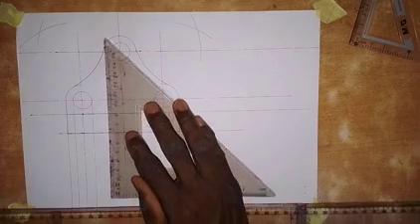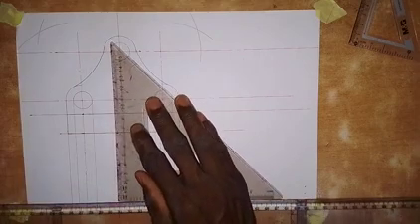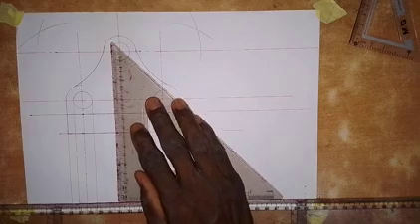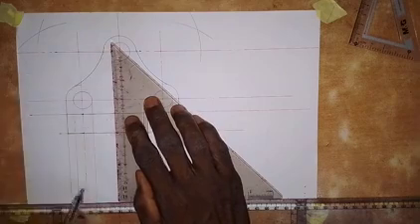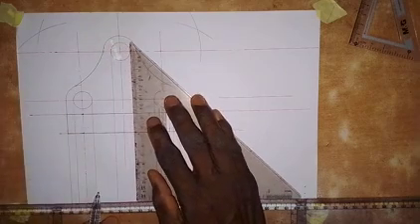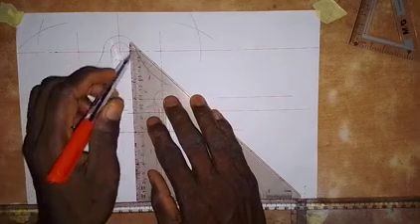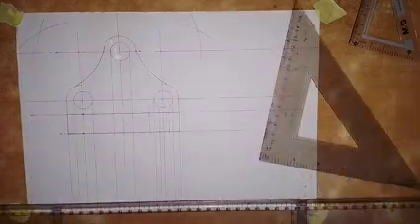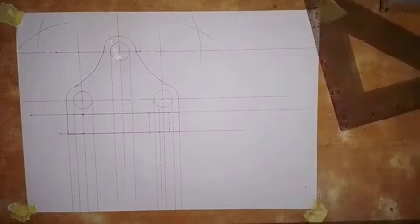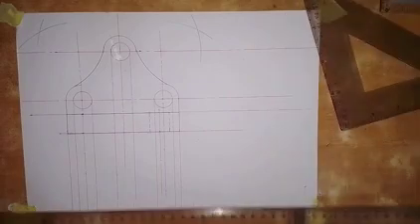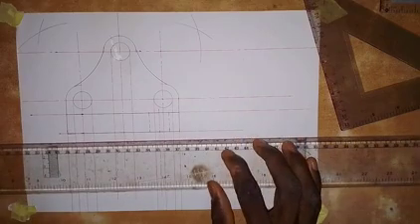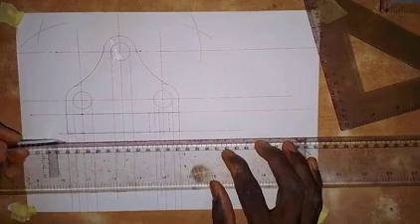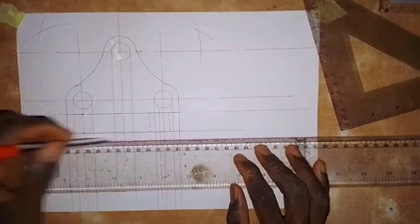And also this circle up here, we need to draw a vertical line from here, so we take it down, and come here and also draw a vertical line down. Alright, for all that we have here, we need to move the front elevation a little bit down to separate the plan from the front elevation. So we are going to draw a horizontal line from here to this side.